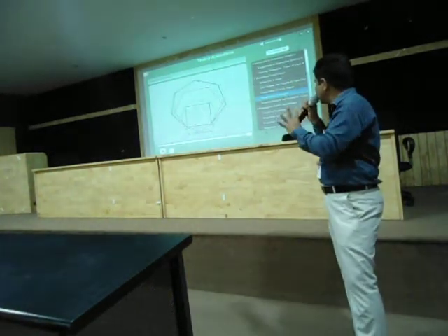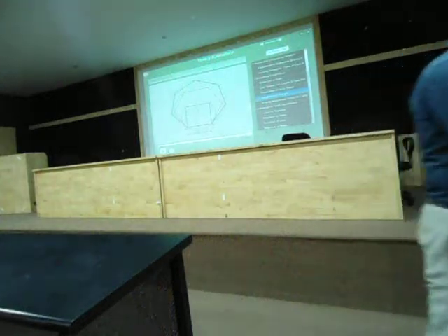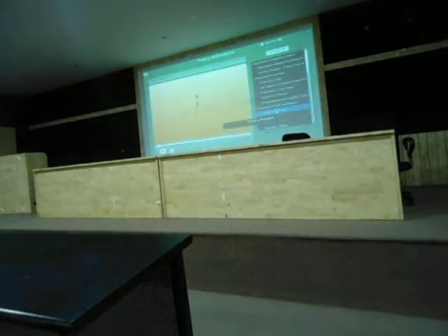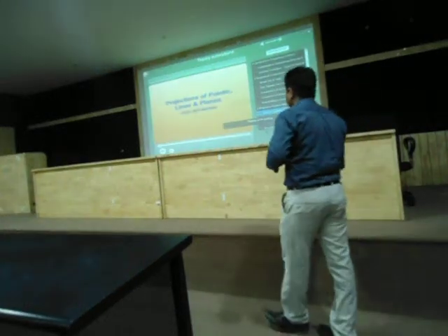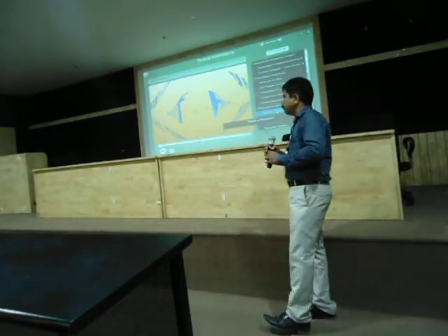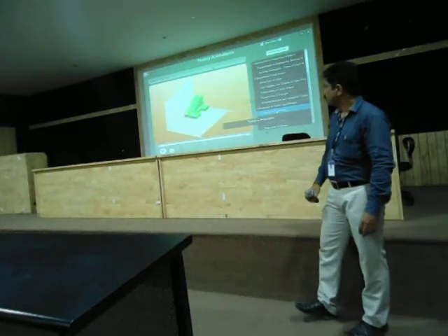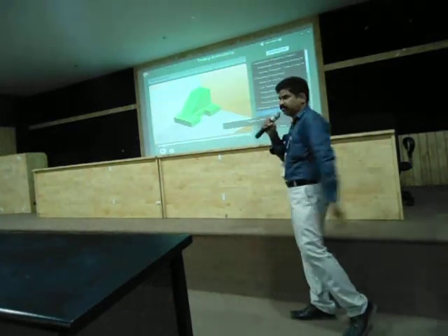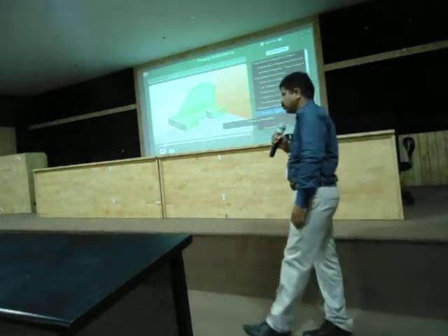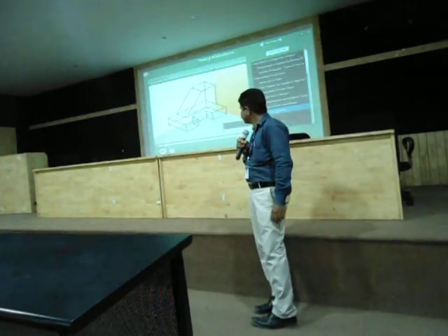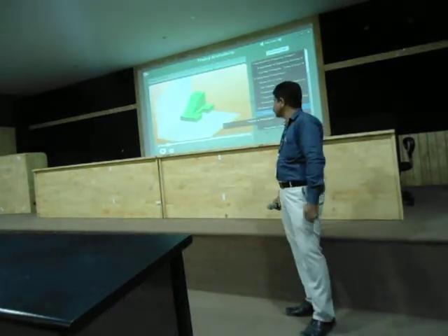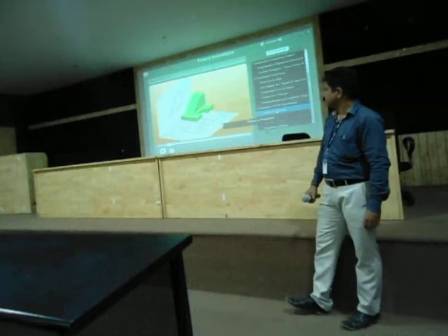Now we will come to the theory of projection, that is projection of points. Hello, today I will take you through the theory of projections. The projection is a process of creating an image of the object on the paper as it appears when observed in a particular vertical plane, horizontal plane and object. An object is represented as a combination of elements: points, lines and planes. Using these elements as tools of drawing, we can project an outline of the object on paper.